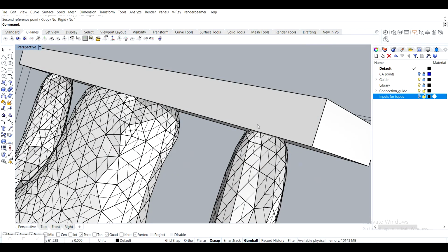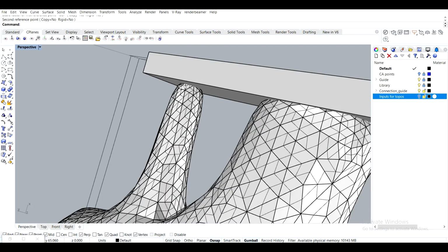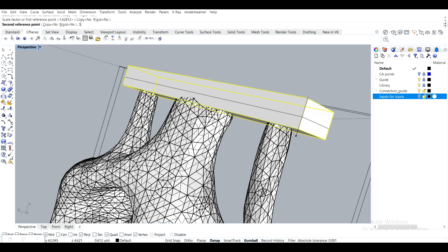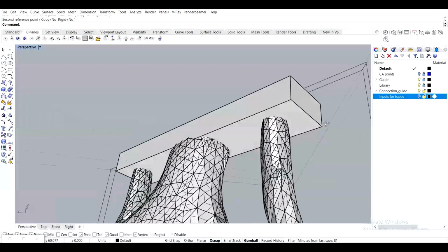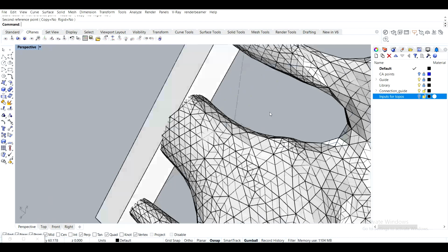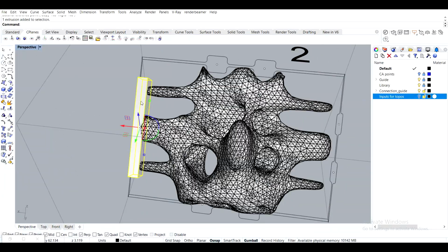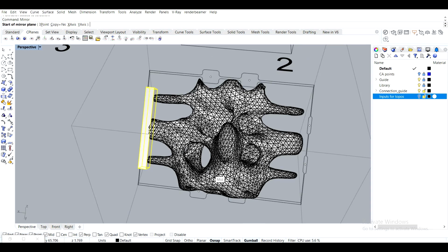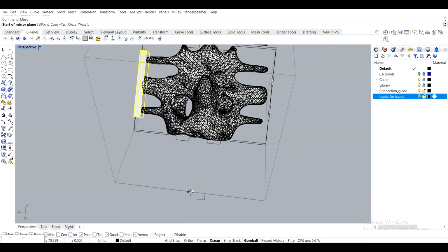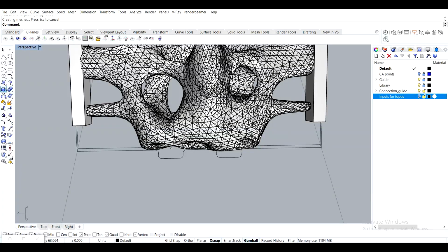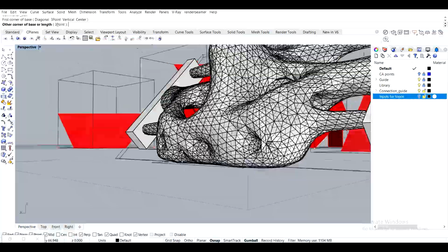Well, it fillets a little bit too early, so actually I do need to use 5 millimeters, which kind of sucks, but 0.5, what the heck. Yeah, that seems okay. So I'll use that. Mirror. You don't need to use the mirror tool, you can just copy it, but I'll be using mirror. And then box for the bottom from here to...